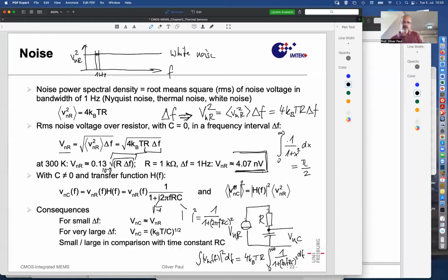At the same time, if you look at the voltage drop at lower frequencies, you will obtain basically this flat portion of the spectrum, which later is dropped down by the action of the capacitor.